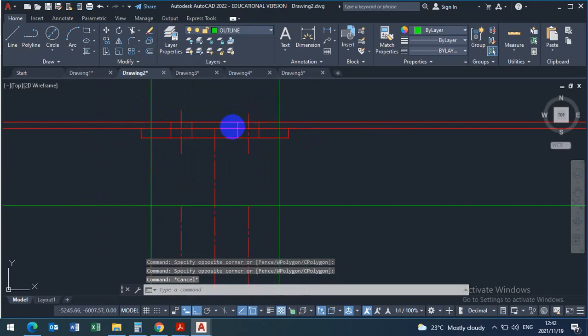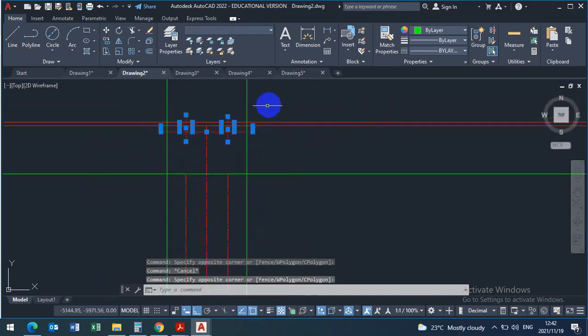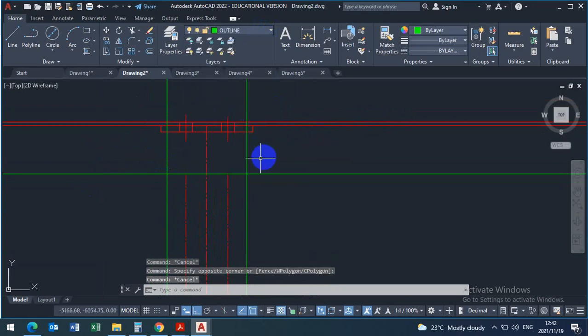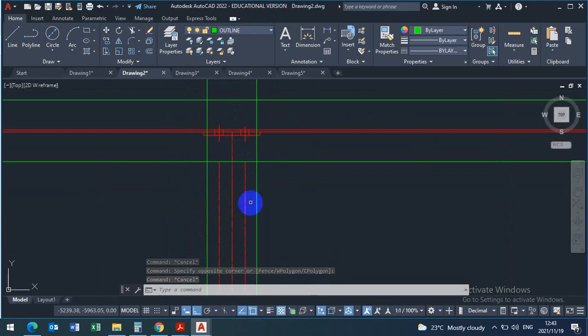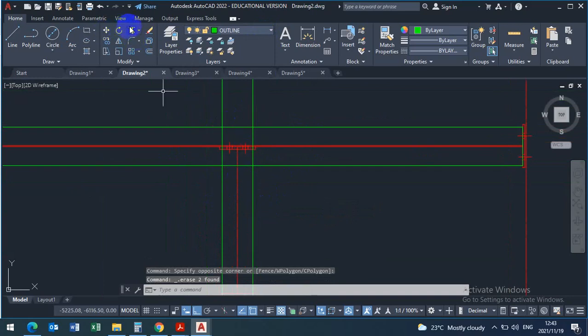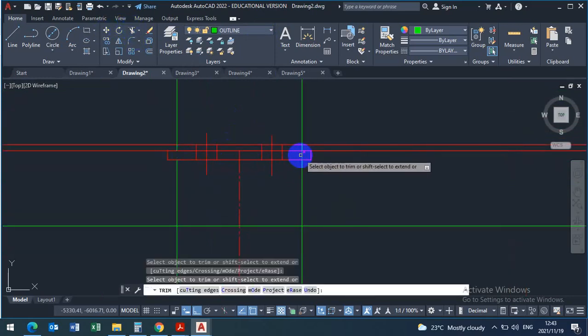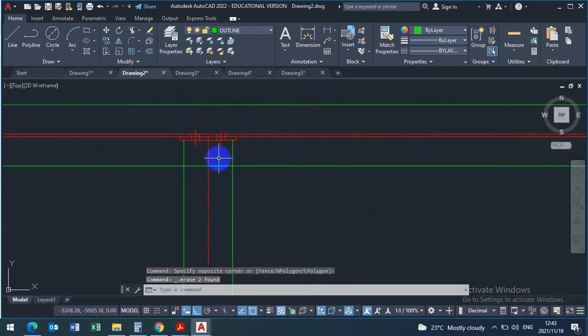Hidden details. All right, so like I said, everything will be hidden. Even the plate will be hidden details, because we are not seeing it, it's under there because of this flange. So all these will be hidden details. You can now delete this. You need to leave that center line, delete that. This is your beam. You need to trim the beam, which ends only here and there.